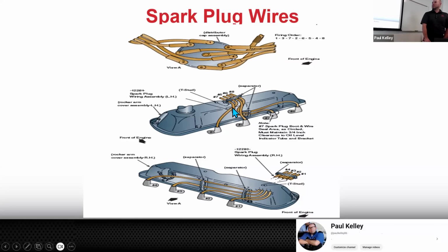If it rubs on the valve cover and wears some of that silicone insulator away, that's a path of least resistance. It's going to arc into that valve cover. So we keep these secondary wires, or high tension leads, or spark plug wires, same words, right? Same parts, different words. We keep those away from problems, especially the exhaust.